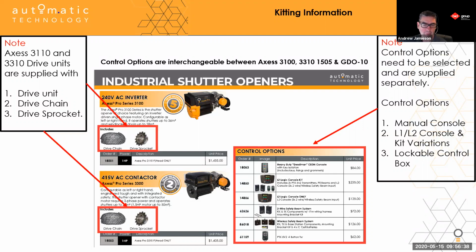You know that it's going to be huge, but the amount of testing we do to quantify, just loading it up on a jig and just putting plates upon plates upon plates, it just gets down to the testing regime. And I say that we target our testing to do the lifetime testing primarily to validate the warranty, and sustainability testing to validate any changes in the design that could possibly affect the performance.